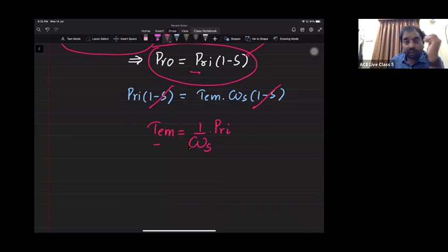Right. But in case of slip ring induction motor, what are you doing? As inductive nature is more at starting, we are adding some high resistance in the rotor circuit at starting. When you are adding some high resistance in the rotor circuit at starting, you are making the rotor circuit highly resistive. Then you can see the active power drawn by the rotor at starting will be very high. The torque which depends on that will be very high, and the starting torque will be very high. Is it clear? Confirm me.